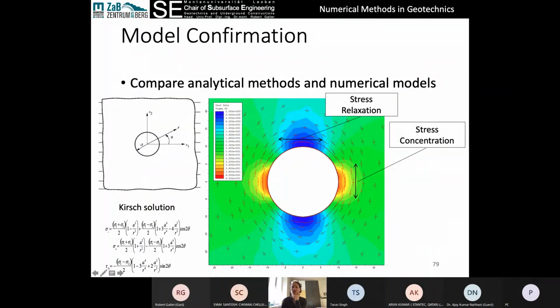When we're in our tunnel, if we're seeing that we have a lot of shear failure here, and tensile failure here and here, that's probably because our stresses are actually oriented a little bit away from the vertical, like this and like this. So we need to rotate our stresses. So stress magnitude and stress orientation also need to be calibrated, and normally with observation.